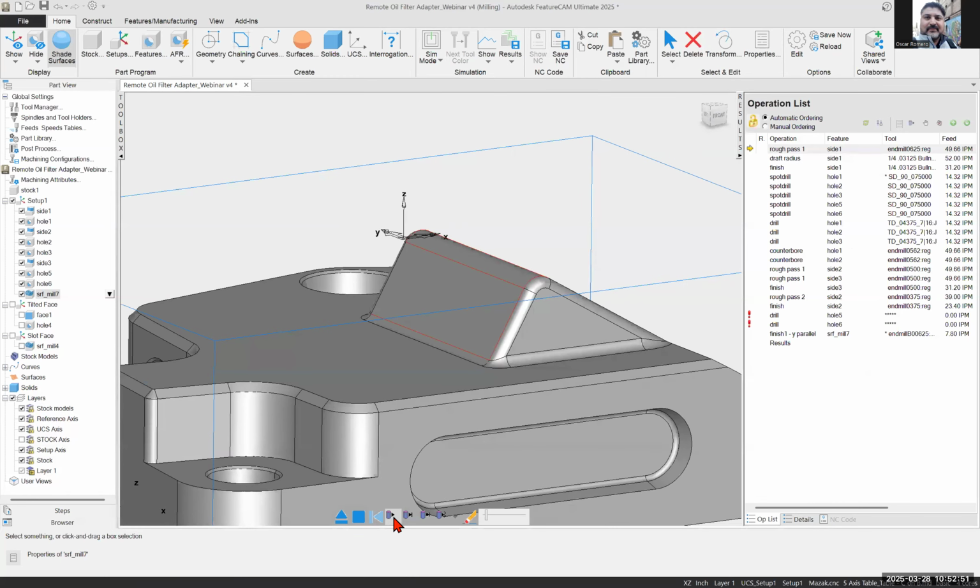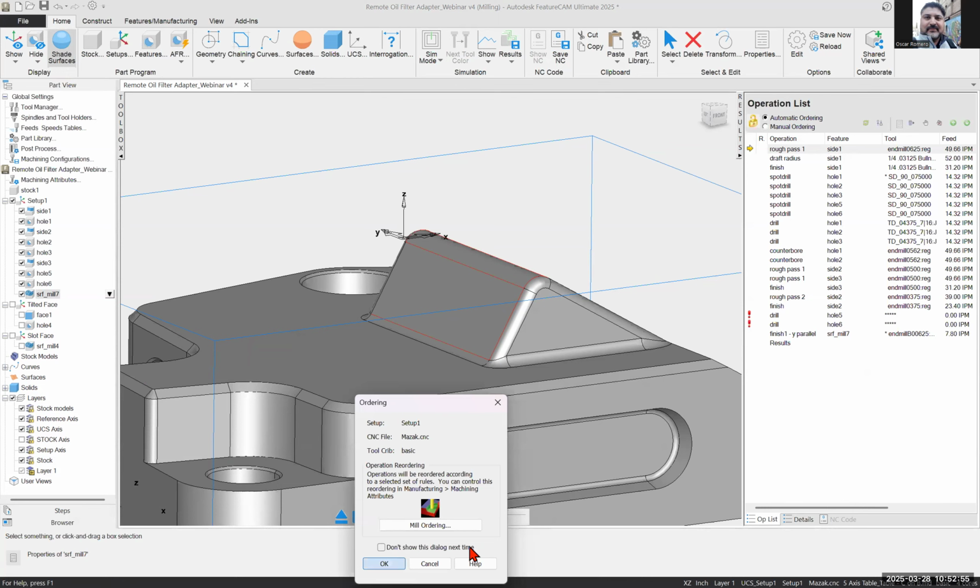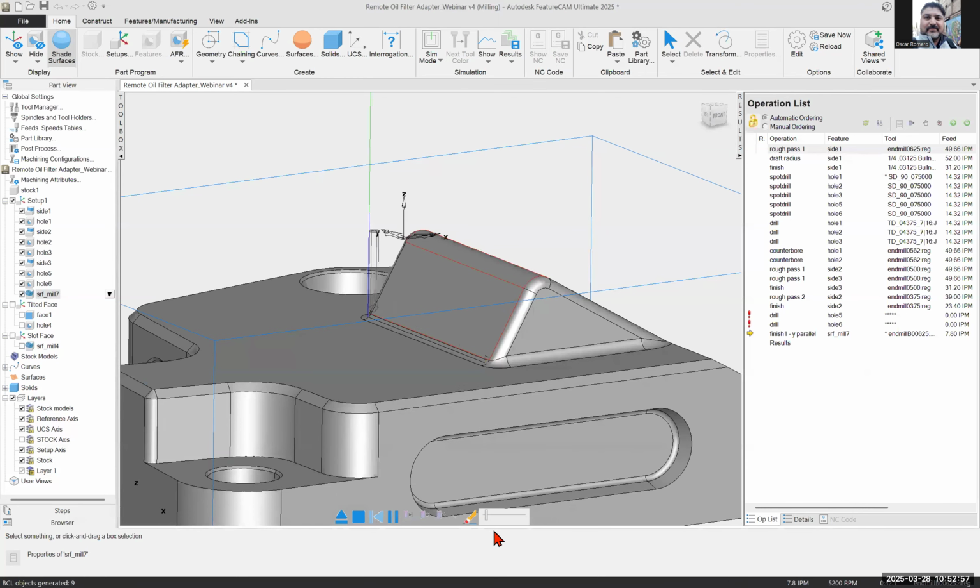So, of course, the desired finish is going to be up to you. That's how we can go and change the step over so we can get a finer finish. We applied a different tool so we can get down all the way into that smaller radius at the bottom. Again, assuming that we've gone ahead and roughed out the material, maybe semi-finished it as well, we can get something like this as a surfacing tool path.